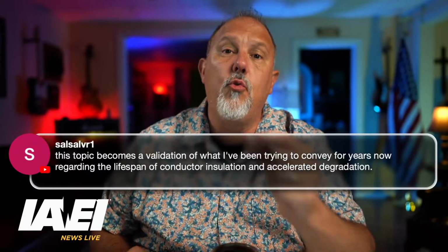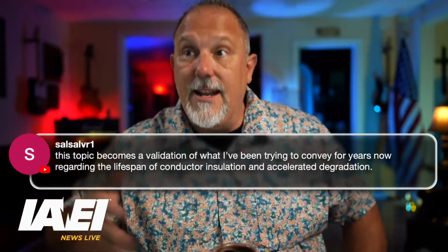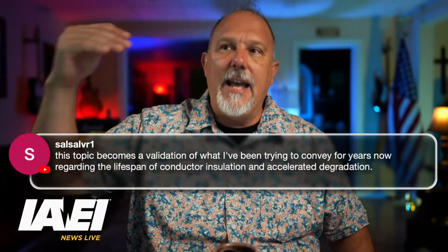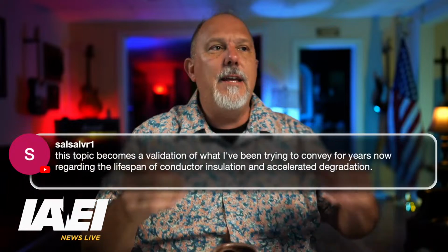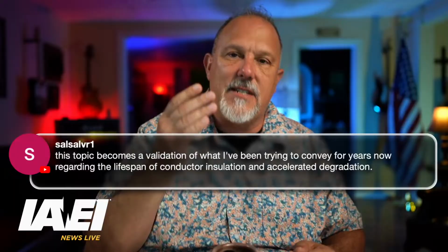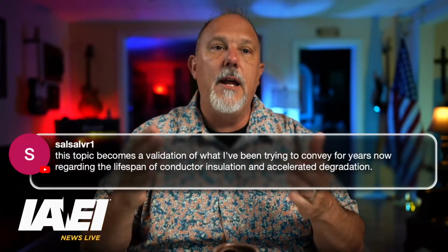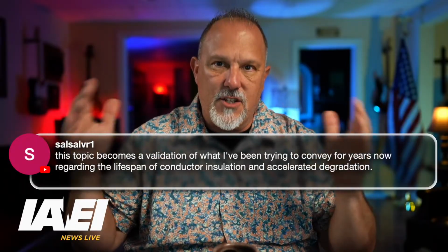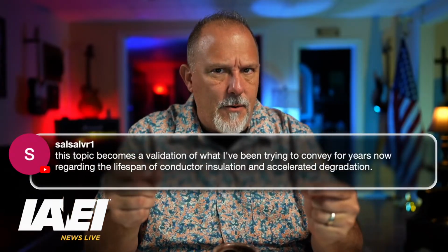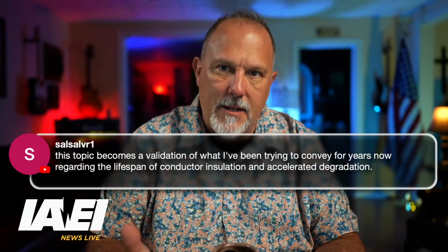But a good question. And I had a really good, healthy discussion with an individual just today. We were talking about what is the impact of the elevated temperature on these components. Say I don't have a 90 degree C, let's say I have a 75 degree C insulated conductor and I put it in 90 degree C, or I use it above its rating. It's not going to immediately fail. What is the long-term implication of the misapplication?